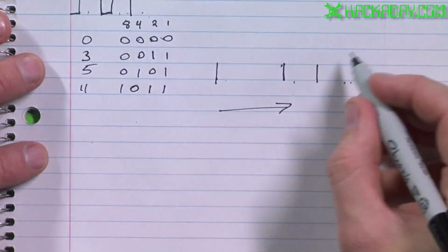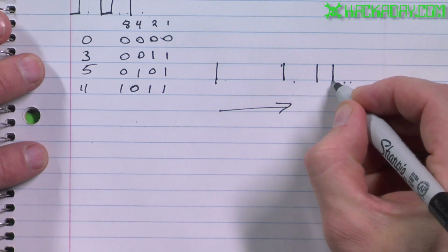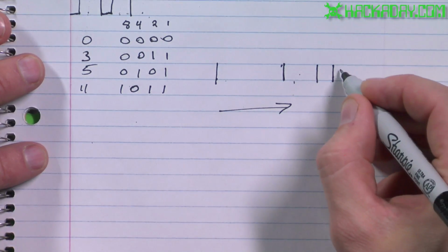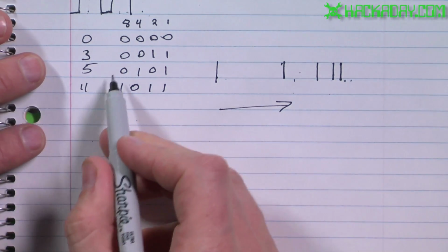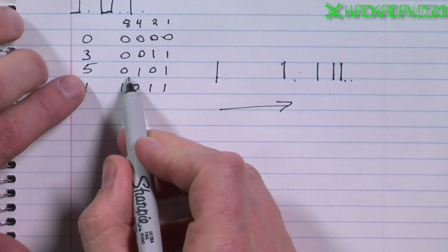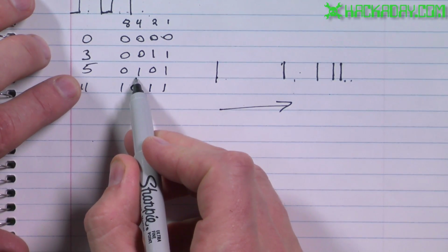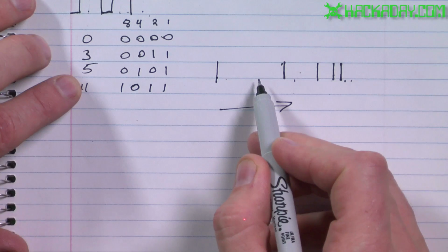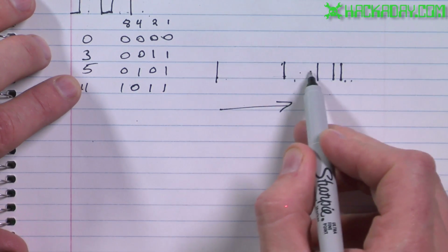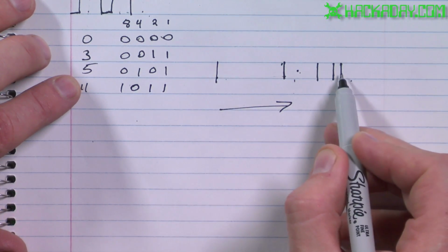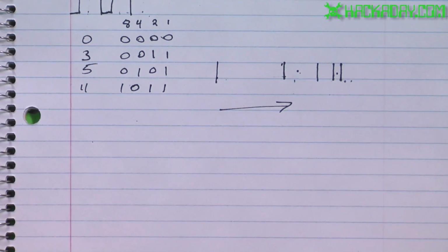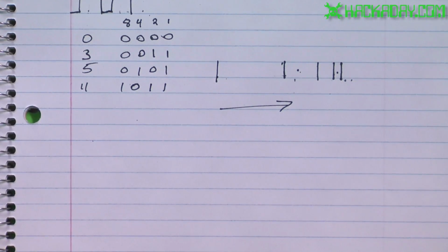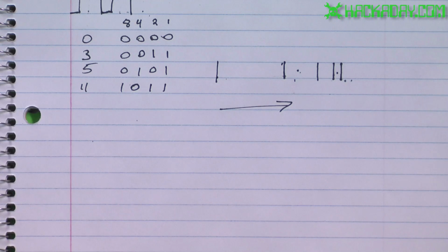And then this bit here will be worth half of this width. And finally, like that. So if I was doing an on time of 5 of 16, this one would be off, this would be on, off, and on like that. That's a bit more of an advanced thing. I haven't told you guys about interrupts yet, but those are some strategies to do pulse width modulation.